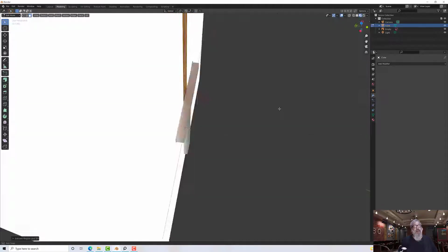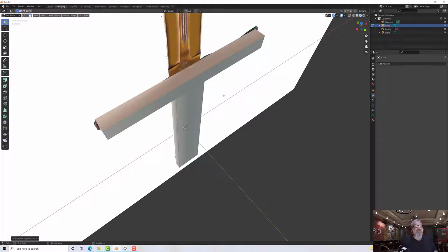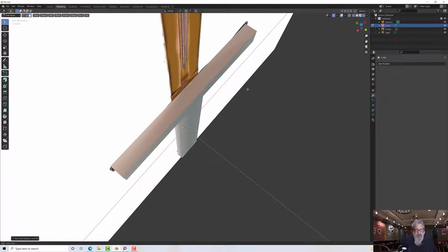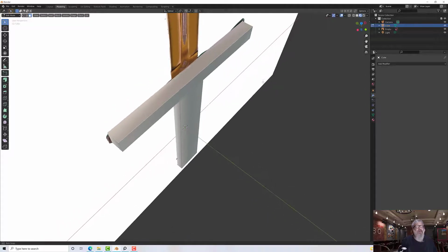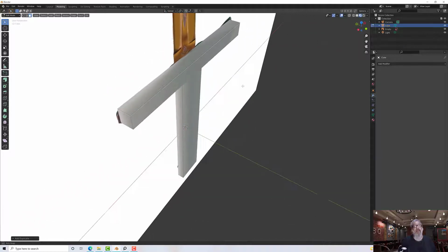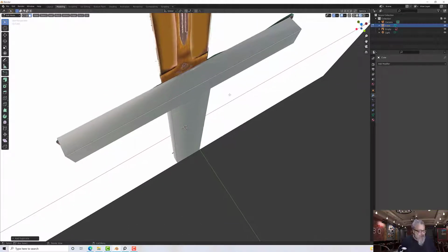And then we're going to do the blade, and this time I want to copy our face, not cut it, because I need this top face for the cross piece. Okay, so to duplicate a selection, I've selected my top polygon here. If I press Shift and D, it will duplicate it, and you'll see it allows you to move it around. I'm just going to move it so it's either just below or preferably dead on,